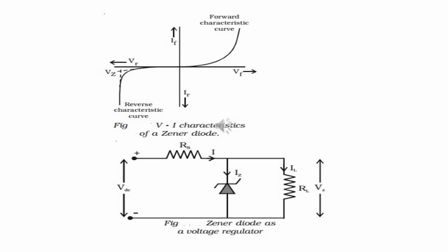A resistance Rs is known as current limiting resistor. Rs is connected in series with the Zener to limit current in the circuit. The output voltage is taken across the load resistance RL. For proper operation, the input voltage Vin must be greater than the Zener diode voltage.